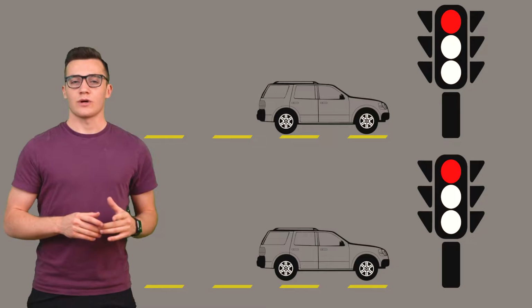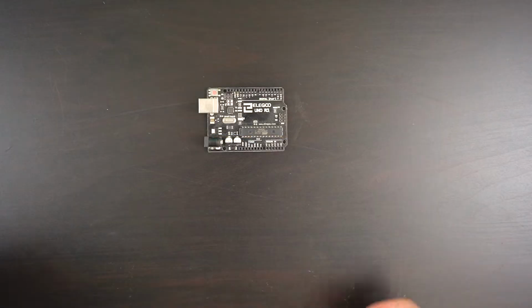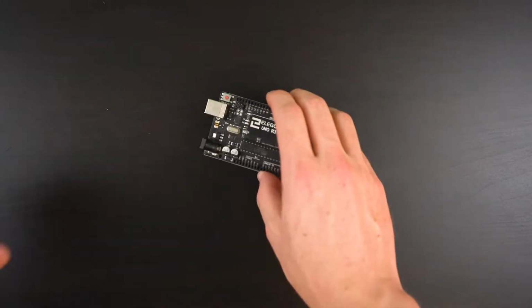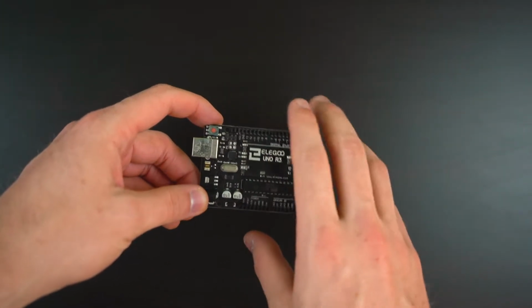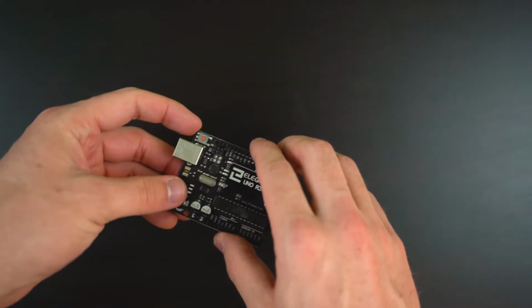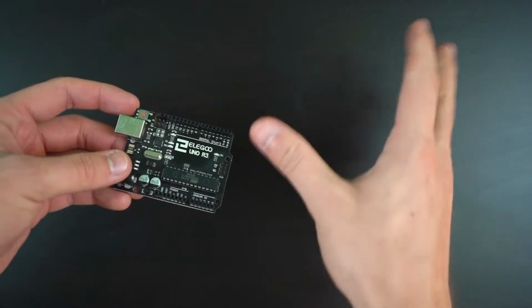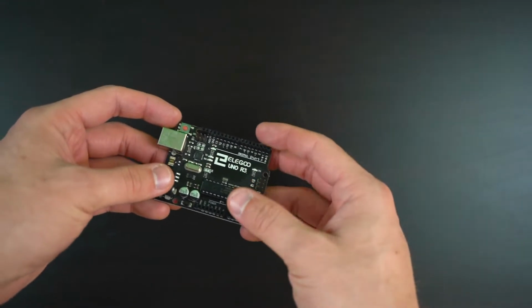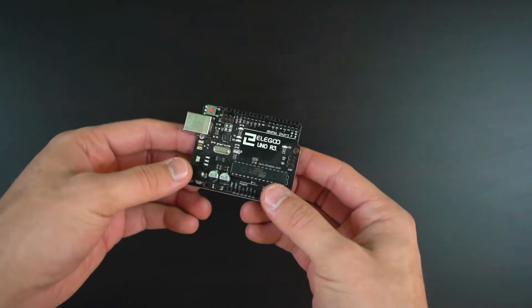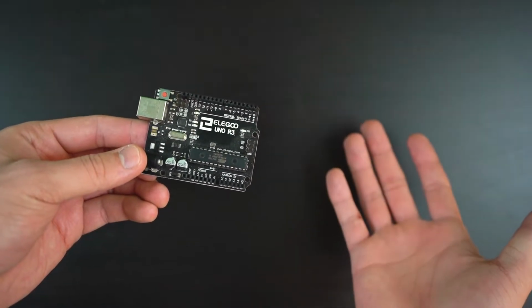Now, let's take a look at what this is like specifically for electronics. So here we have an Arduino microcontroller. And guess what? These output pins, which can go to things like speakers or LEDs, can only put out either 0 volts or 5 volts. And that means we could flash our light at full brightness by cycling between 0 and 5 volts, which could be useful, but that doesn't help us out if we're trying to shine the light at a dimmed brightness that isn't the maximum light that the LED can output.